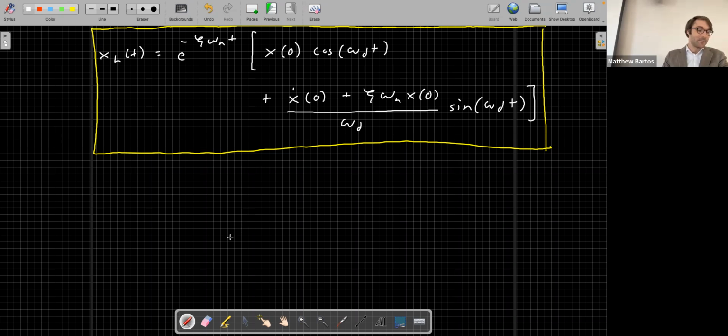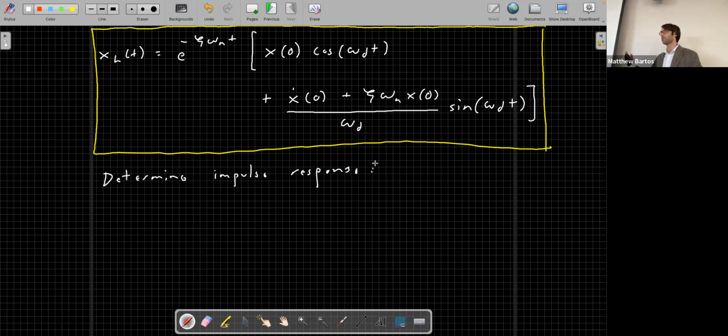And you will see why it may not be the approach you would like to use. Okay, so first, let's look at what the impulse response of the system is. And for the RC circuit, I showed you that the impulse response could be thought of as essentially being equivalent to the response of the system to some initial condition. For a structural system, it's very much the same. And I won't go through this derivation just because we don't have time. It's very similar to the explanation I showed you for the RC circuit. But for a structural system, the impulse response